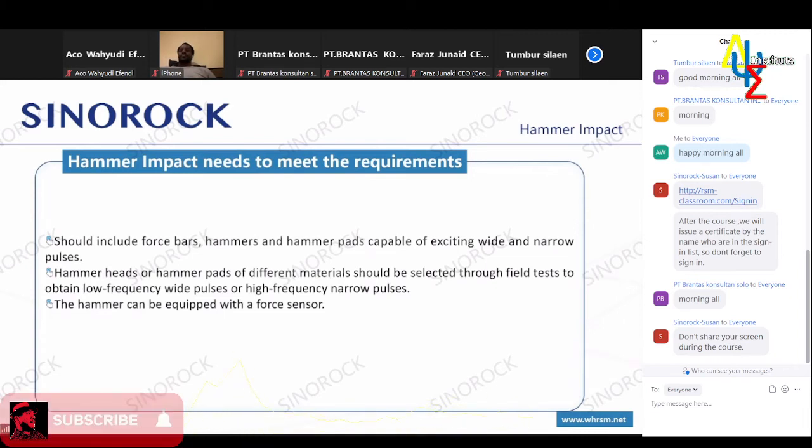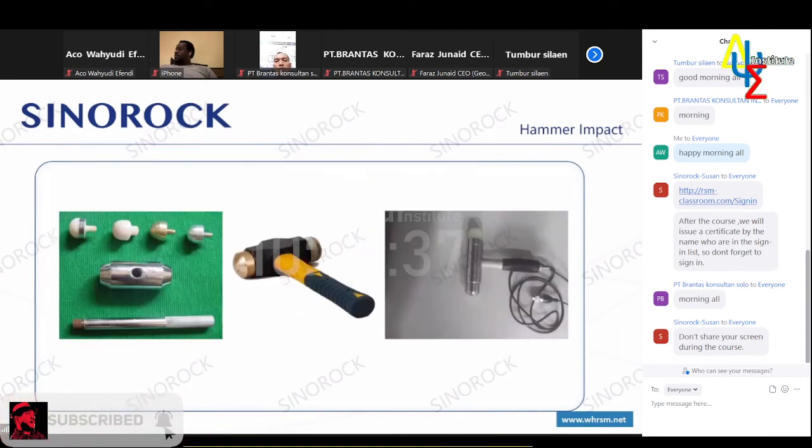However, the hammer and hammer pad need to be selected through field experiments. The choice of hammer is not only related to the pile, but also related to the soil around the pile and other geological conditions, whether the stress wave meets the requirements, and whether it can spread to the bottom of the pile. There is no very empirical law, so it can only be evaluated and judged through field experiments. There are several types of hammers.